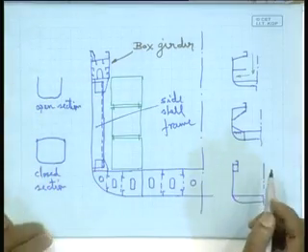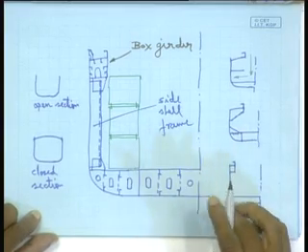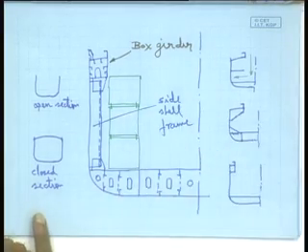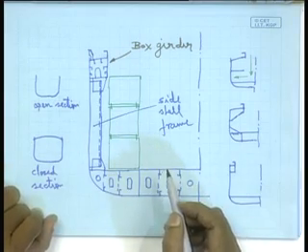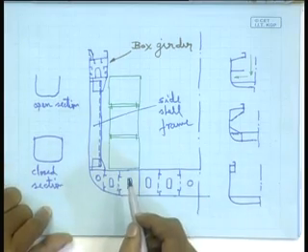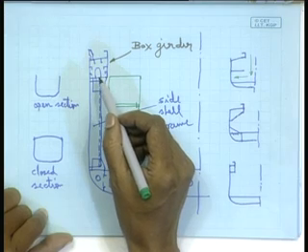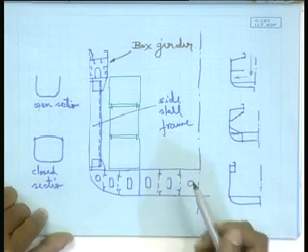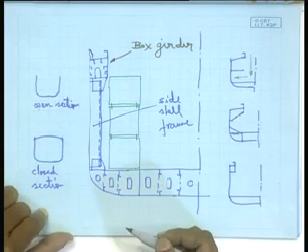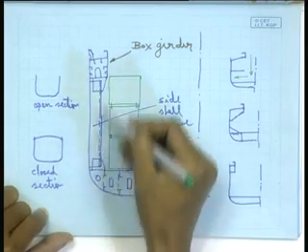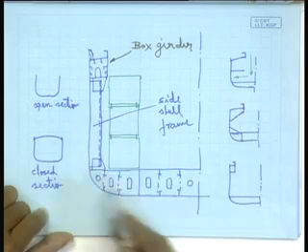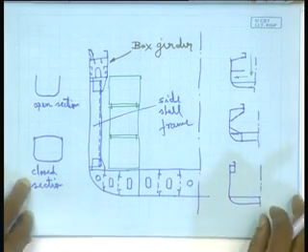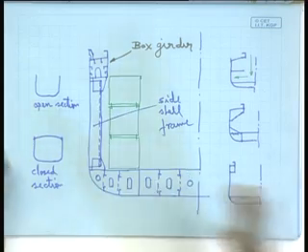Anyway, so here we can see that because of the loading, I mean the functional requirement, you need a big opening. For a big opening, there is a problem of torsional strength that is solved by providing a heavy box girder arrangement at the top deck level. Side shell is transversely stiffened, right, with heavy bracketing at both the ends, and the bottom part is a double bottom like in any other vessel. So, with this one can go up to a certain size.